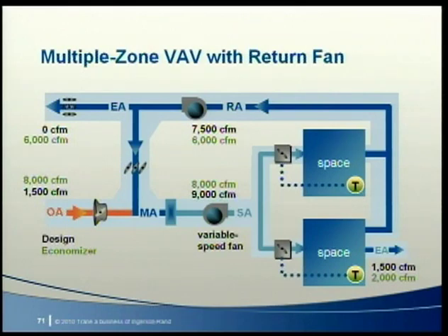can accommodate it. Some VAV systems use return ducts, so they need a return fan rather than a relief fan. The supply fan takes care of all supply side pressure drops, while the return fan takes care of the return side. Supply fan selection is similar to our previous discussion, but with lower total static pressure. Return fan selection, however, can be tricky, primarily due to morning warm-up operation.